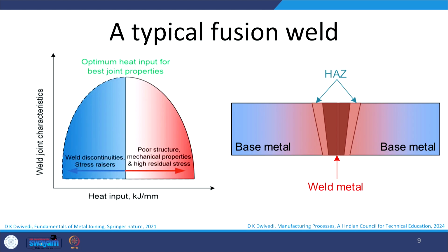Okay. So, whether it is solid state welding or fusion welding, heat input must be optimum. What is the meaning of this? If in fusion welding the heat input is less, it means the heat required is not being supplied. That will cause the development of defective welds; it will not lead to through thickness penetration, and so an unwelded section will be left. This will be the defect called lack of penetration. This is a very common issue: if the heat is not proper, it will promote a lot of defects in the weld joint.